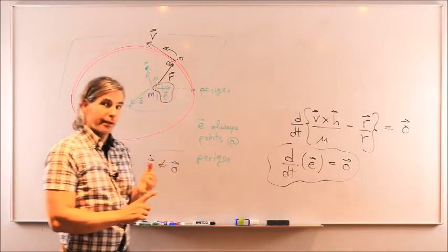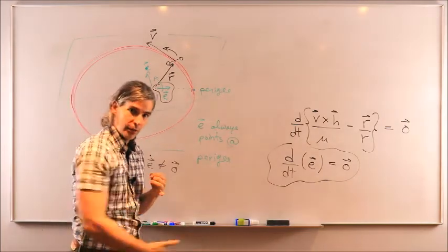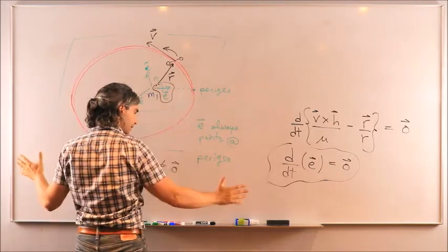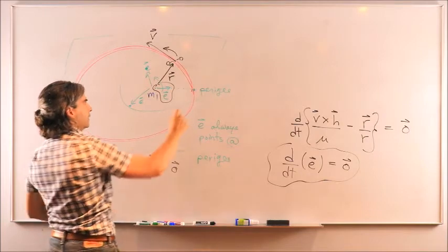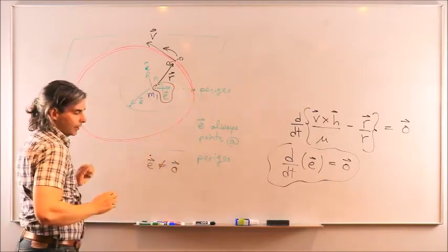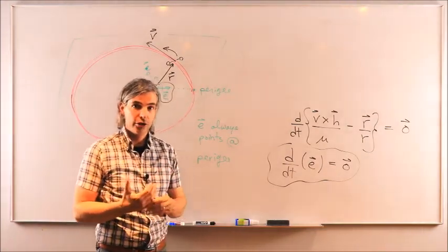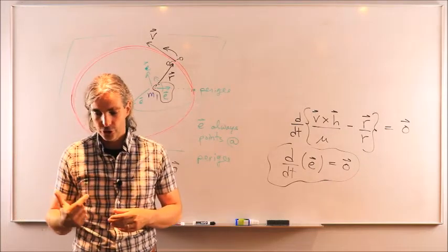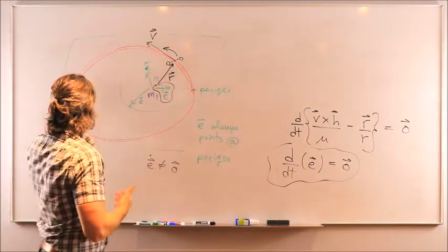So again, to summarize, the takeaway of the fundamental integrals concept is that the plane in which the spacecraft evolves around M1 is set in stone, and you could pretend that this is the whiteboard plane. Second thing is that position and speed have to be scaled accordingly to ensure that the net orbital energy, which is v squared over 2 minus mu over r, is constant throughout the orbit.